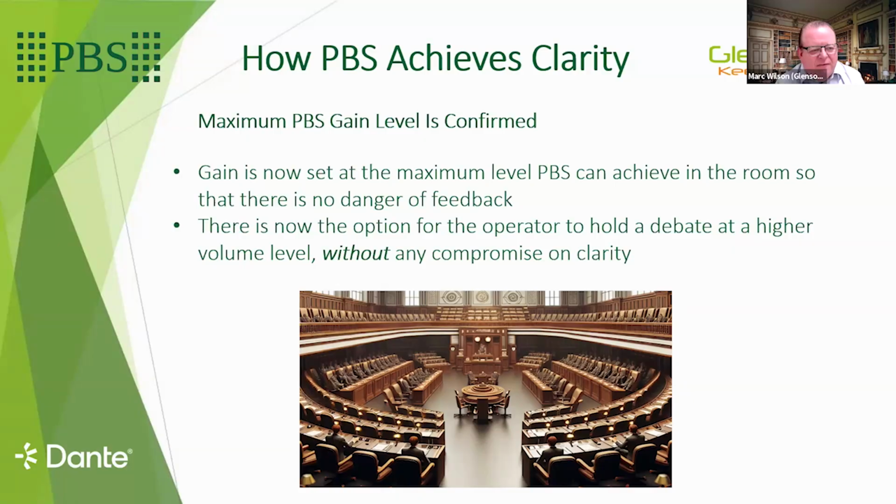So the need for high level is actually reduced, because if you can hear it clearly, there's less of an inclination just to make it louder. So we typically have plenty of volume available if it's ever required, and we have the ceiling of operation for the system that will not be approaching any feedback issues, because we've already notch filtered out the problem areas. We've got a frequency shifter. The room is EQ'd. We put the profile of the room together without making any compromises on the clarity in the room.